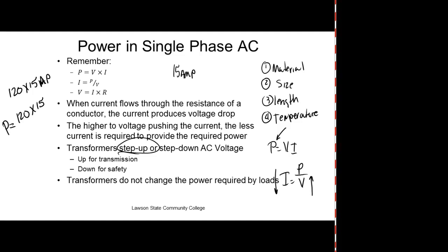The feed for your transformers is between 1,000 volts or 2,200 volts, which is still pretty dang dangerous, right? But you look at those wires up there, they're little old tiny things handling all that power. Why? Because it's such high voltage, right? You understand that? And then it comes into your house, and then that transformer steps it down to the 240 and 120 that we use in our house. And the wires down drop from our house are bigger than the wires up there providing the power. Why? Because the wires providing the power are at a lot higher voltage. Does that make sense? And that's the advantage of AC.